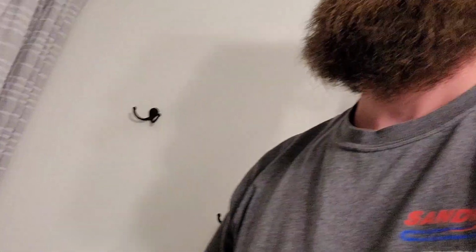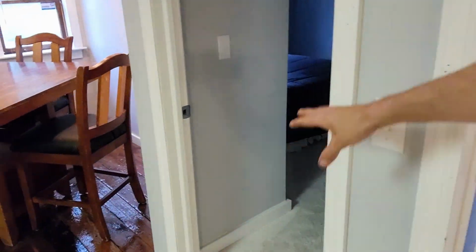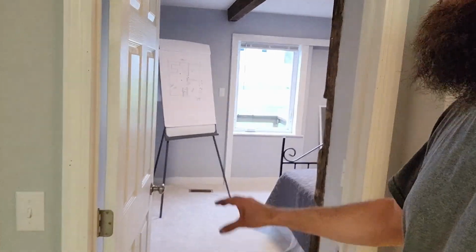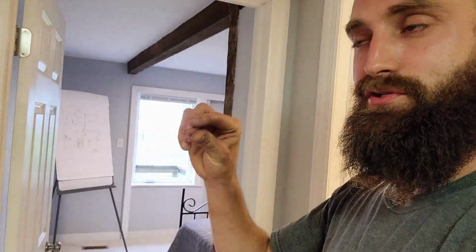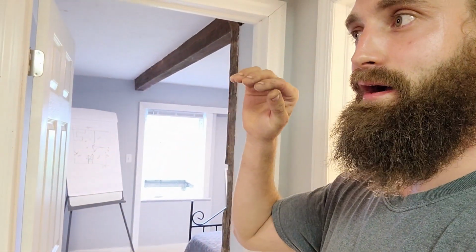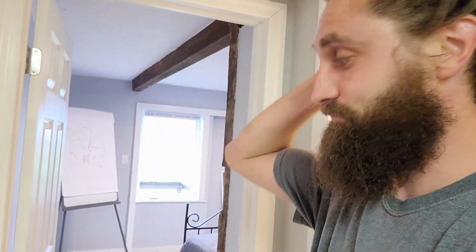Again, on a small area like this, it's not going to be a deal breaker between a 2-ton and a 2.5 ton. But if we were dealing with a 4,000 square foot building where half of it had this type of floor and the other half was a traditional carpeted framed out floor, it will make a difference, especially in your duct calculation. So take note of all of your floors, okay?